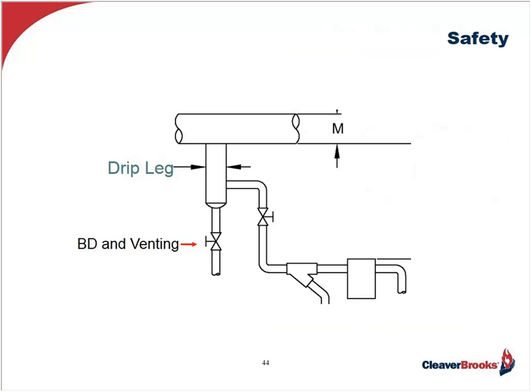For instance, I showed you earlier how we would like to see drip pockets sized, where the trap should be located, and of course, the pocket should have a drain valve at its bottom for air removal when a system is starting up or restarting after a cool down. It's also there to rid the pocket of sediment and debris which could ultimately foul up the trap.